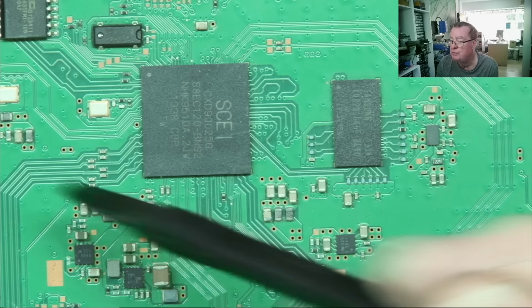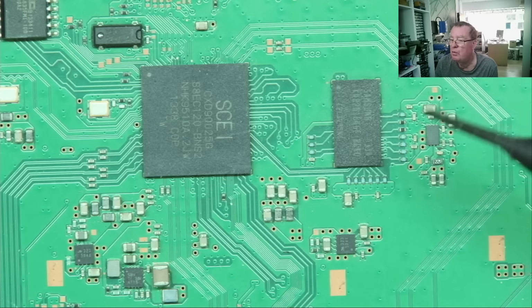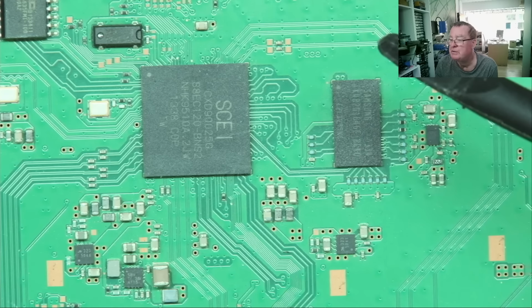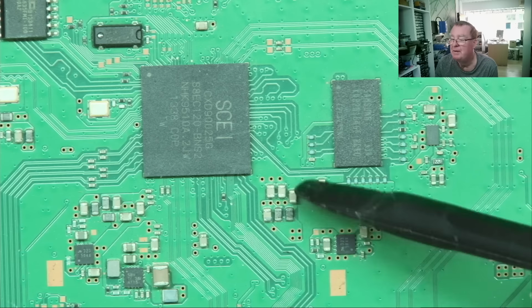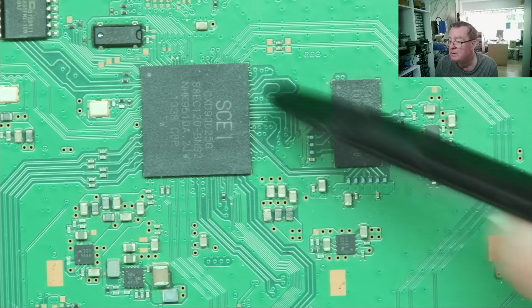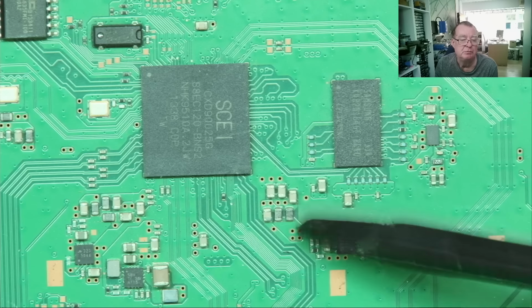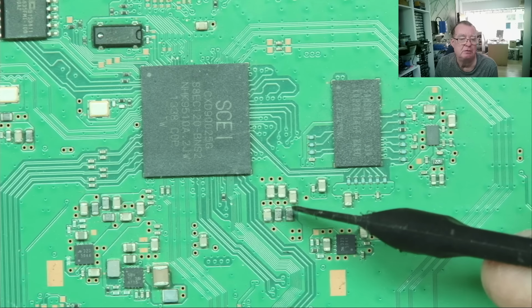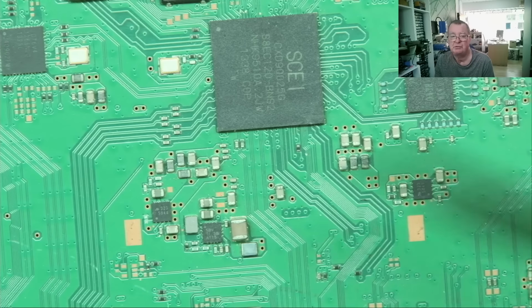The reason these normally fail is because of physical shock to the device or heating and cooling. So they're in an area of the circuit near to something which is running warm normally, and during power cycling on and off, the thing is warming up and cooling down, warming up and cooling down. And because the ceramic expands and contracts at a different rate to the metal ends and to the PCB, this can cause them to fracture. Now, you might think that a capacitor which fractures, it's got a crack through it, goes open circuit. But in the case of these, they don't, they go short circuit.